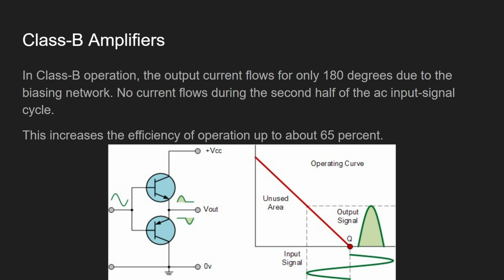So that's why if we just use Class B amplifiers, we may combine both of them. One to amplify the positive signal and one to amplify the negative signal, okay? But you remember that Class B only does half of the job. Not that efficient, but better than Class A, worse than Class C, okay? This is the characteristics of Class B. They only do half of the work.